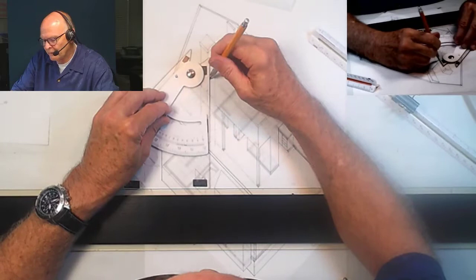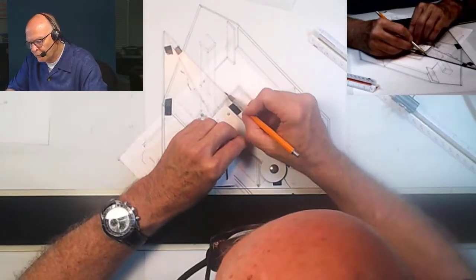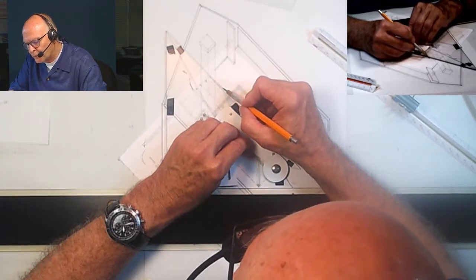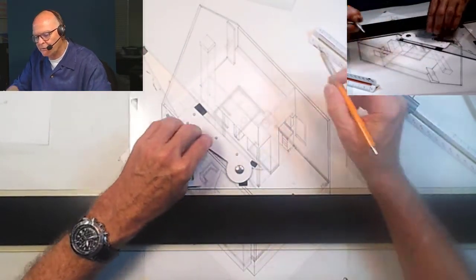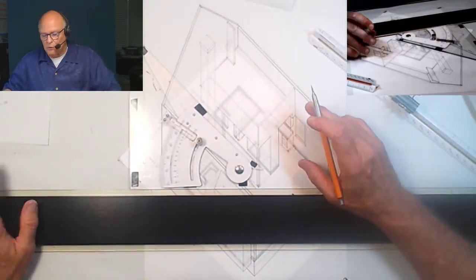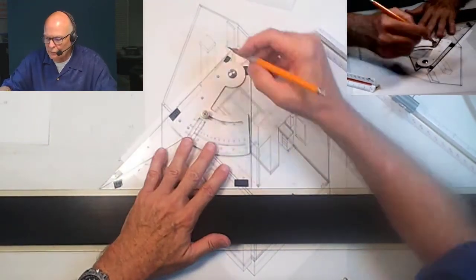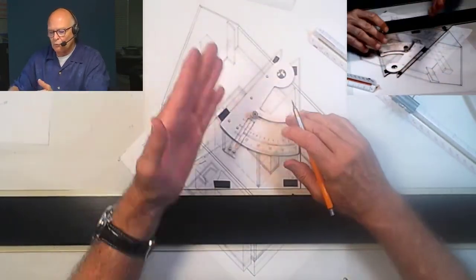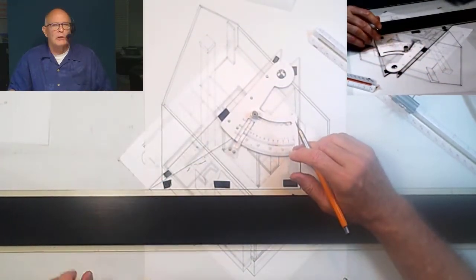And we're going to extend that wall up to where it intersects the top line, and what you're going to observe is it's hiding behind the chimney. It's like, well, why are we bothering with that, Secor? Because we have to. We're not going to have it in the finished drawing, but I need to refer to it because this railing wall is going to emerge from the backside.